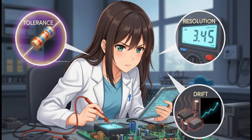Now, even if you do everything perfectly, your measured values will probably never match your theoretical predictions exactly. Don't panic. This isn't failure. It's just reality. Your job is to identify and document these sources of error, things like component tolerance, the limited resolution of your tools, and even how heat can change resistance while you're measuring.